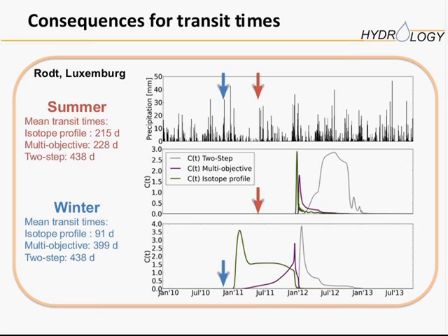And do you never get to those ranges even in the sort of drier end in the soils? No, that's interesting. People usually think if the soil moisture is low, the vapor content is low, but even in soils with only a water content of 5-6%, the concentration of water vapor in the soil is still around 90 to 95% relative saturation, right?